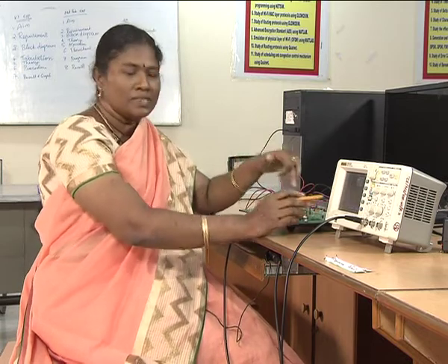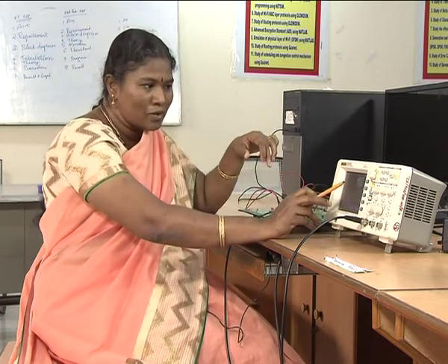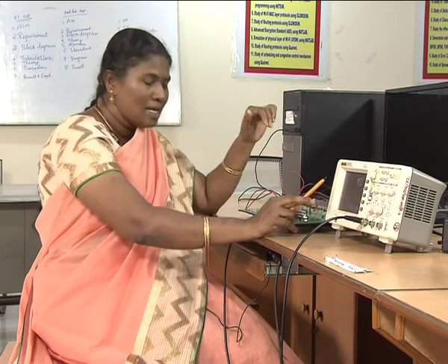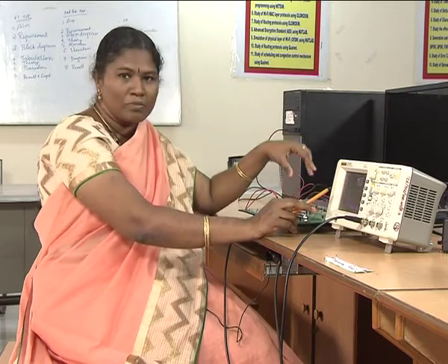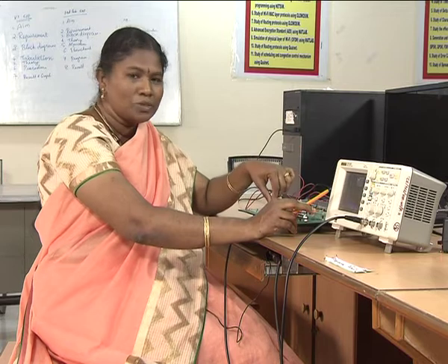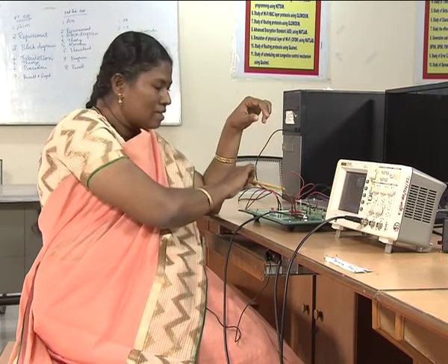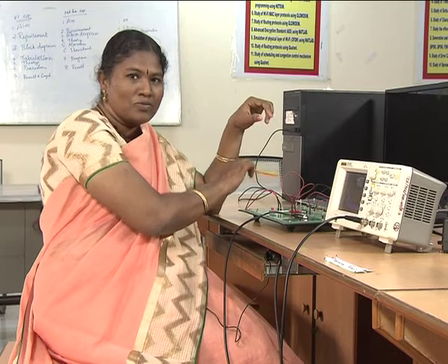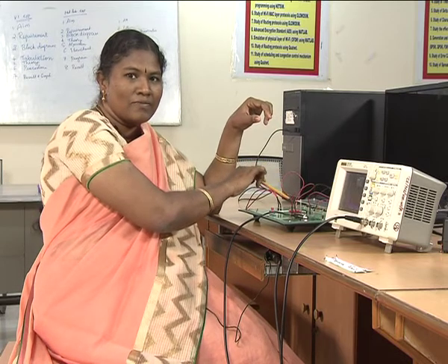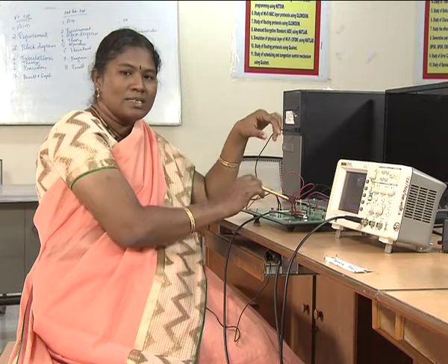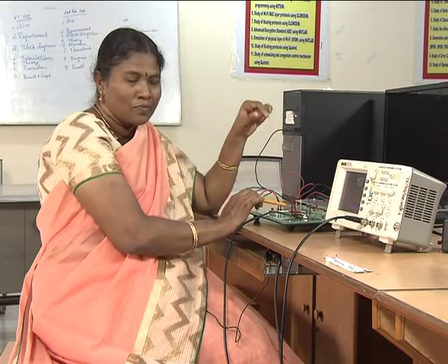The free running frequency that we have set was nearly 99 kilohertz. After measuring that, just give the input with some amplitude and frequency. With respect to the kit we can set 2 frequencies, one is 500 Hz and the other is 5 kHz. So, we have set 5 kilohertz and given it as input to the VCO.